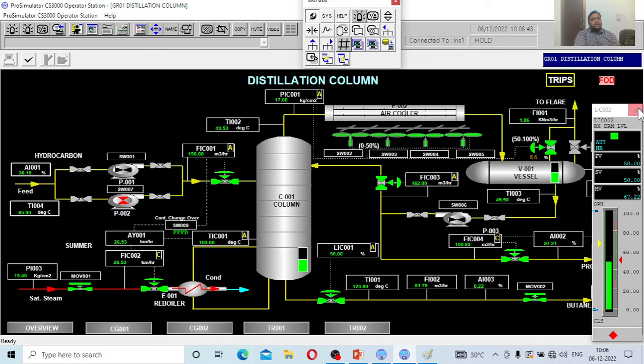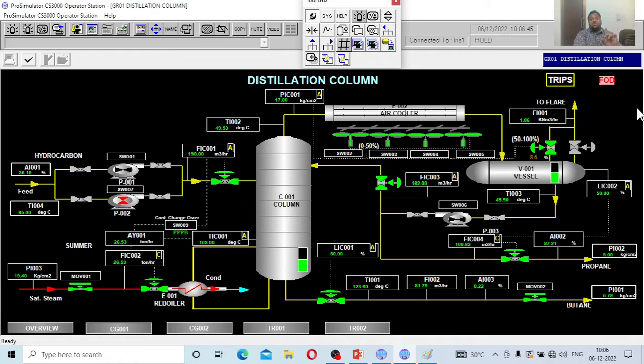Why do people go for the cascade control system? I told you, for better control, because level control is a lazy control system, and this makes it much more active. The secondary controller measures the flow and controls accordingly. Please go to my cascade control system video to know more about it. That means presently you have seen this particular cascade. This is called the cascade control system.